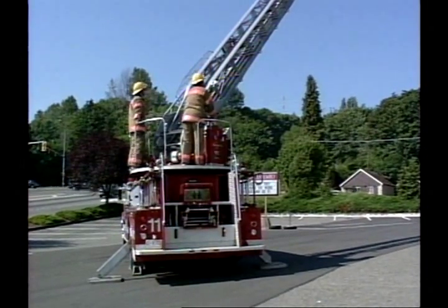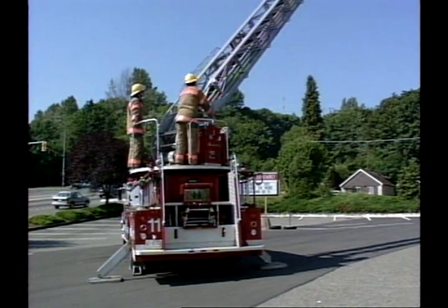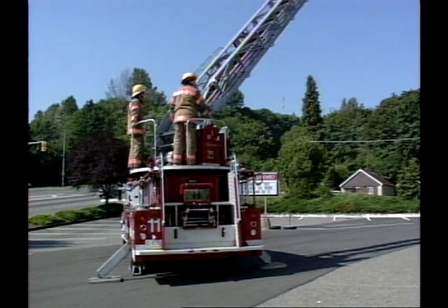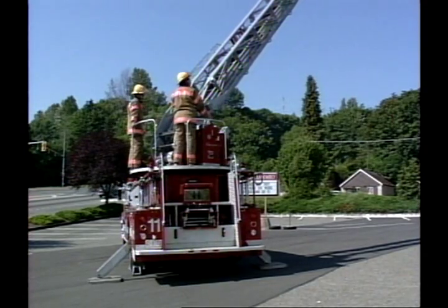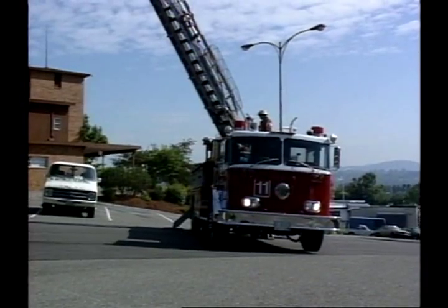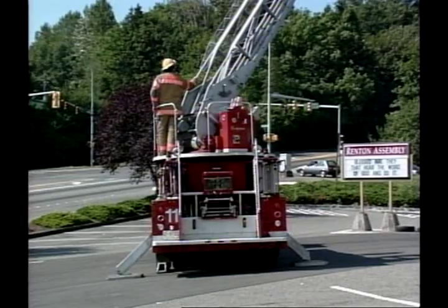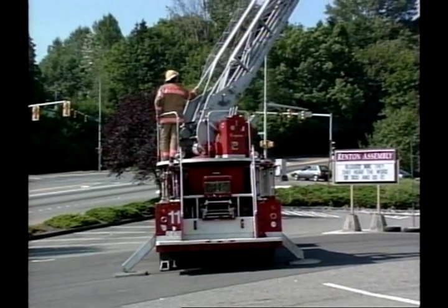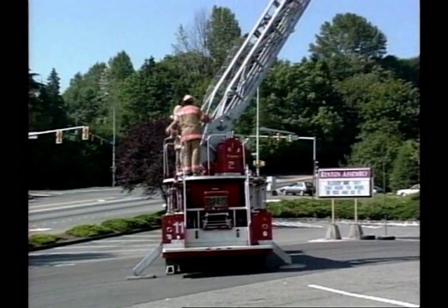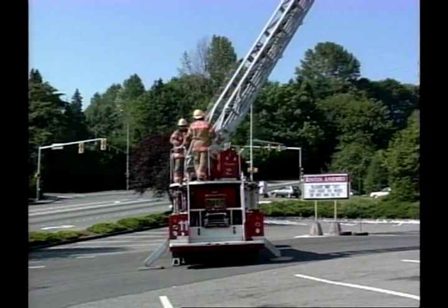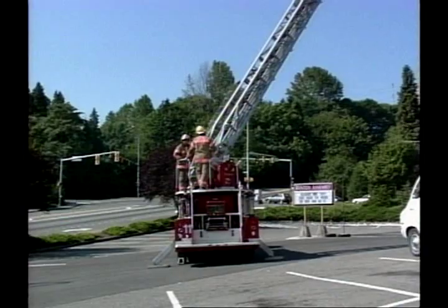In all cases, consult the manufacturer's recommendations for the maximum extension and loading amounts when operating on uneven terrain. Remember, manufacturers' guidelines vary widely. For example, at least one manufacturer requires you to lower the stabilizers on the low side of the truck first on a laterally uneven grade.